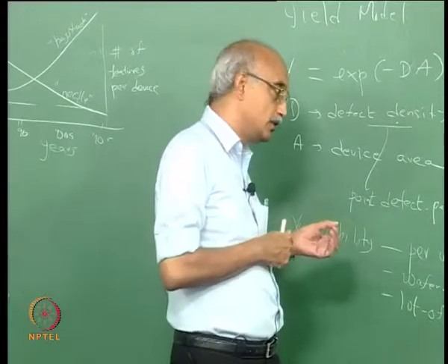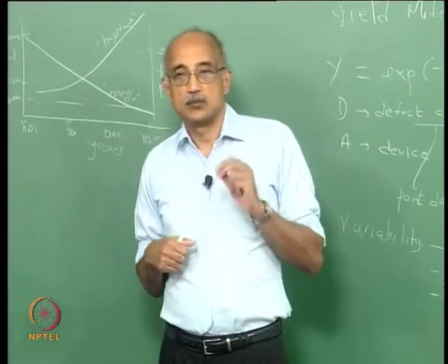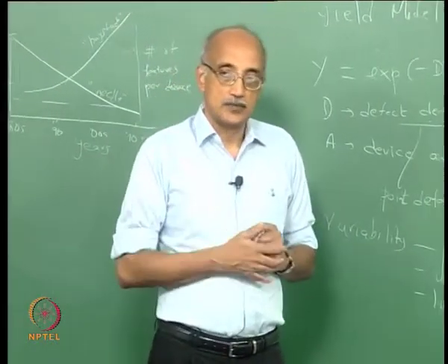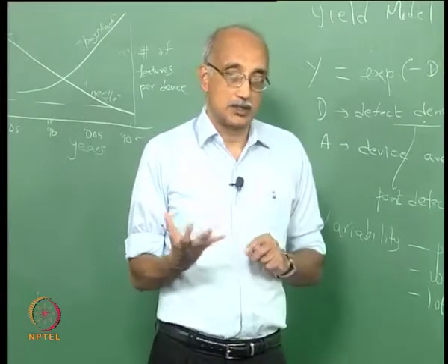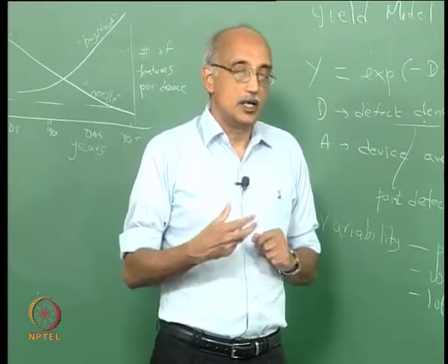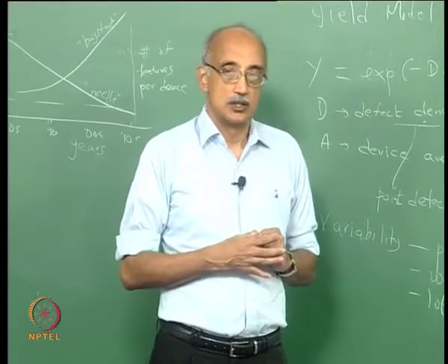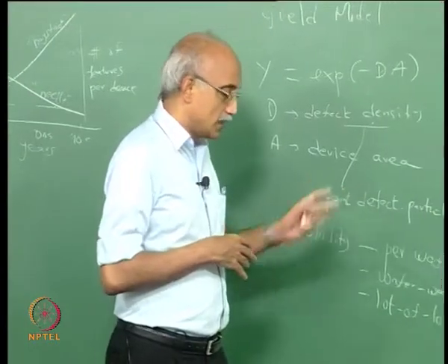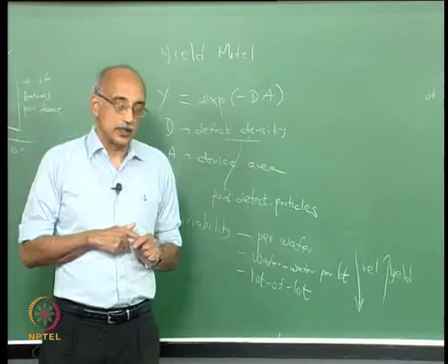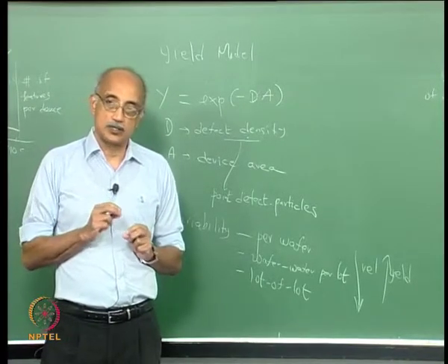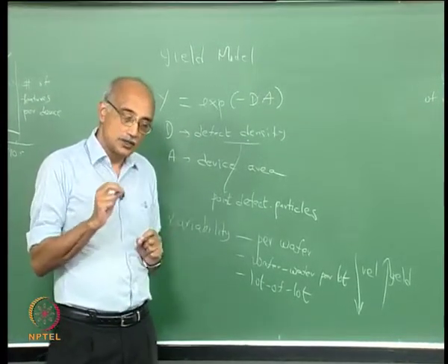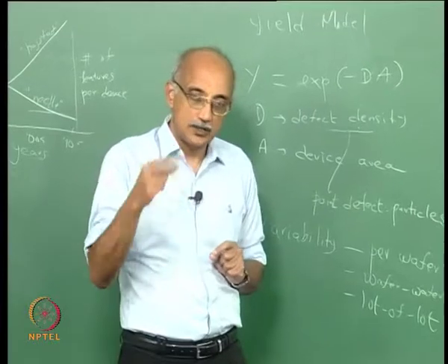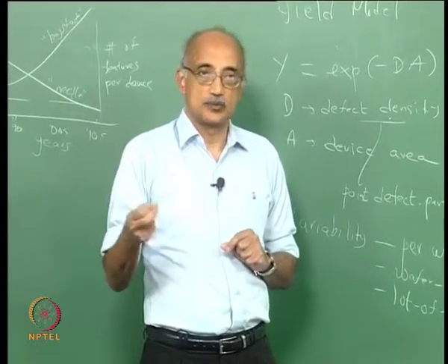So, if you have a good and thorough understanding of particle behavior, particle characteristics, particle properties, you can incorporate this knowledge, this insight in the design phase of your product, and thereby essentially eliminate problems that can happen later in your production, where the cost impact can be very, very high. So, we have looked at some examples here of where particles on products can cause problems. The reason that it is important to identify particle related issues early in the design phases is that it becomes harder and harder to make changes once the process matures.